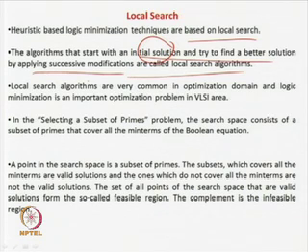Then you can also minimize two terms, like for example, if you have x a plus x bar a, then it will be a into x plus x bar, that is equal to a dot 1, that is equal to a. So, this type of small minimization you can do, so that your number of product terms or number of literals in the product terms will keep on decreasing. Such small modifications you keep on doing. That is called successive modification, and it is nothing but local search algorithms.